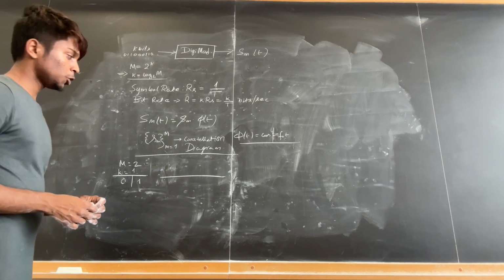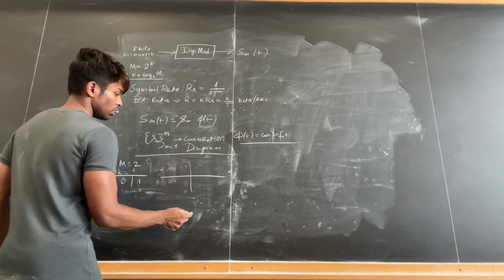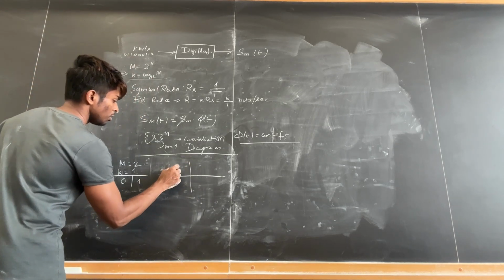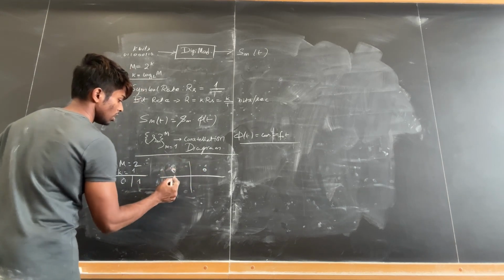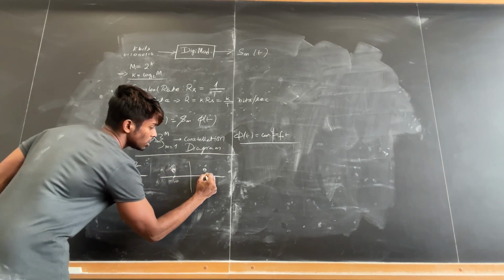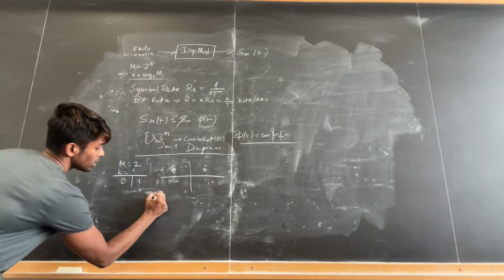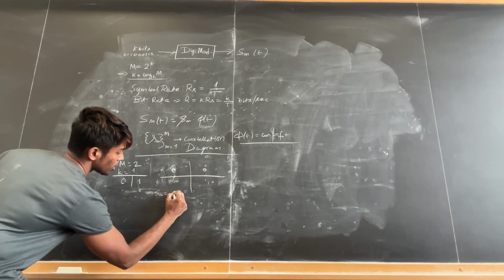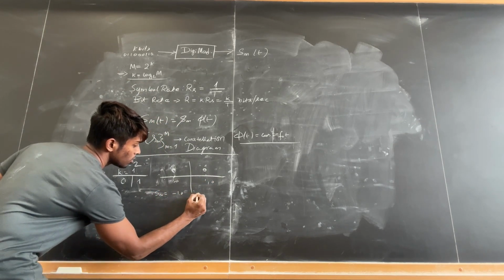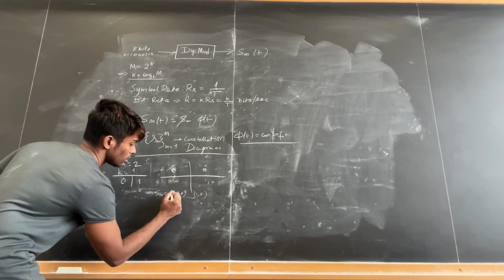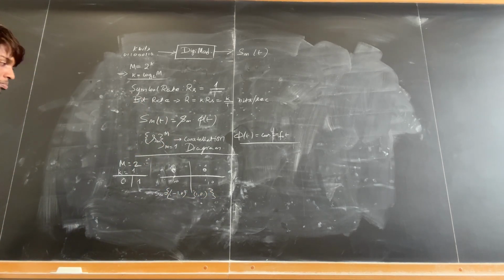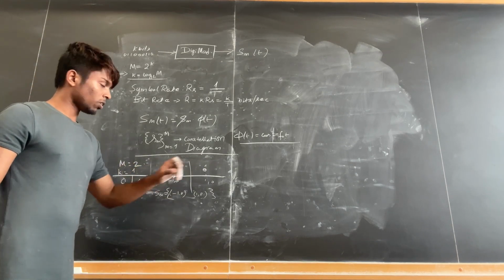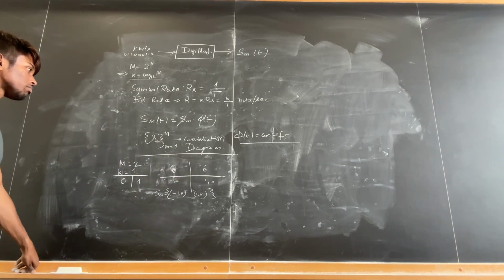Suppose in the pulse amplitude modulation case, here we shall put the symbol 0 and here we shall put the symbol 1. So this is (-1, 0) and this is (1, 0). So s_m is a set of values, the coordinates (-1, 0) and (1, 0). That is the support of the constellation, and this diagram we draw is the constellation diagram.